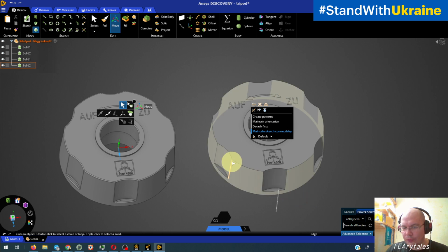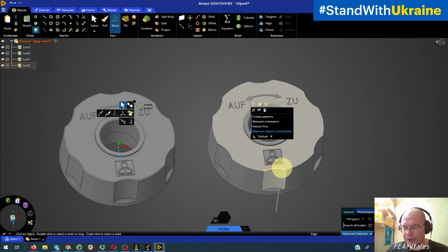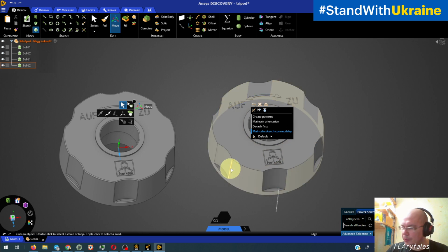Imagine all fillets are 0.5 millimeter, half of a millimeter. We select those fillets and create a selection list based on that filter, and we have a problem. We select based on this one, and it doesn't have a problem.